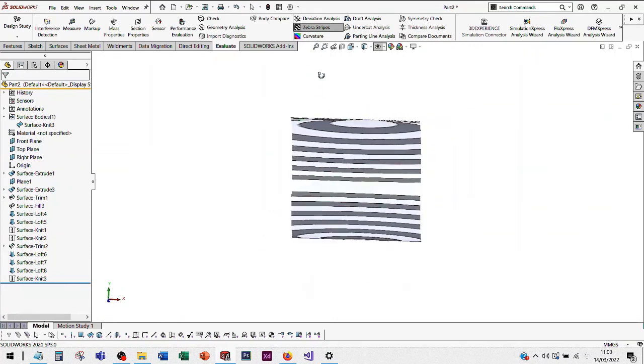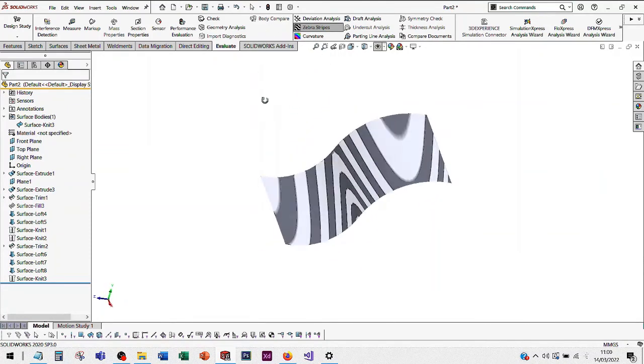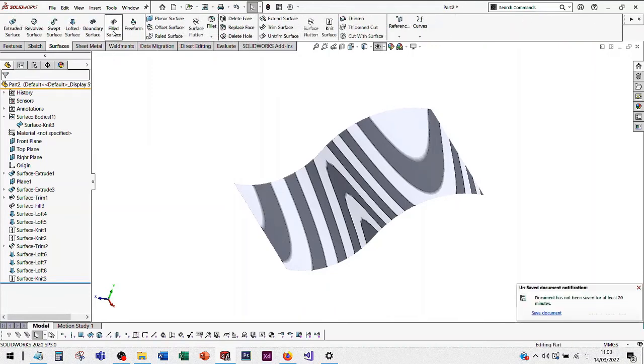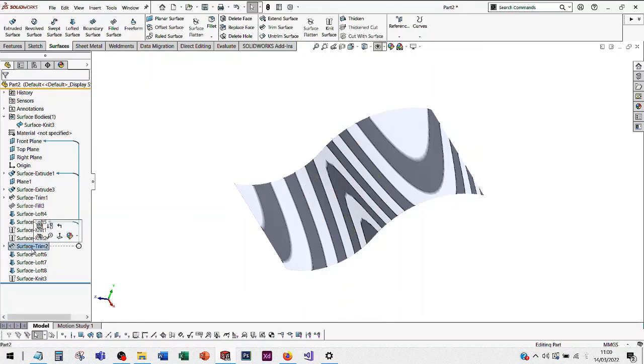As you can see, the idea of surfacing is to rebuild surfaces, perhaps create smooth blends in the right way. It's not always a case of throwing or slapping on a patched surface, or what we were looking at here, which is a filled surface. Sometimes the better treatments are to actually do the work and create multiple surfaces, trim back where you need to trim back, and achieve what you're looking to achieve.